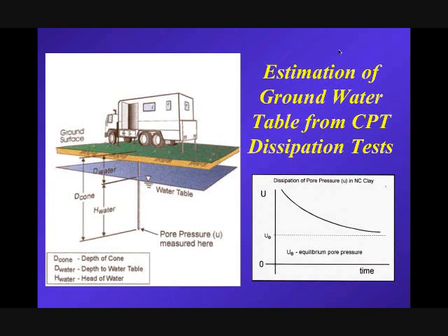Now, of course, if you're pushing in a clean sand, the permeability is so high that the excess pore pressures dissipate essentially while you're pushing. So you can actually measure the equilibrium piezometric profile while you're pushing the cone. And if the groundwater conditions are hydrostatic, you'll actually measure the hydrostatic groundwater conditions while you're pushing the cone in these clean sands. But in soft clays, you can generate large excess pore pressures. In very soft, sensitive clays, you can generate very large excess pore pressures.